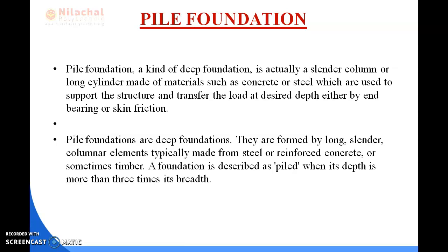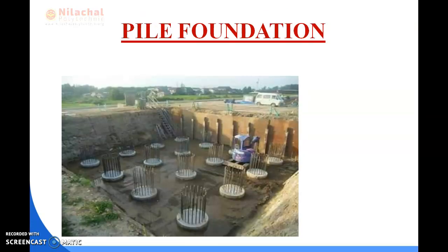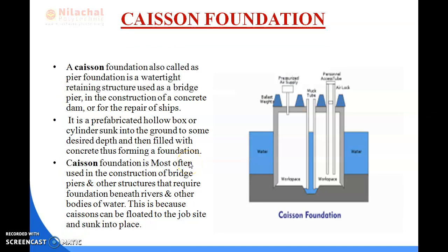Okay, and pile foundations are deep foundations. They are formed by long slender column elements, typically made from steel or reinforced concrete or sometimes timber, and a foundation is described as piled when its depth is more than 3 times its breadth. Okay, and this is the picture of your pile foundation. See here, the circular shapes are made. Come to the next one.